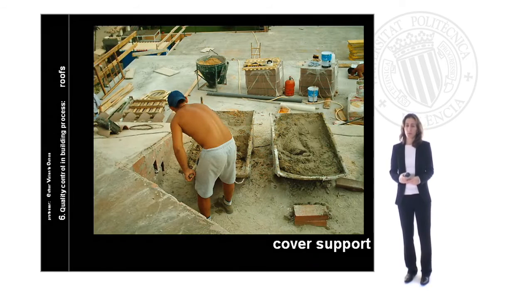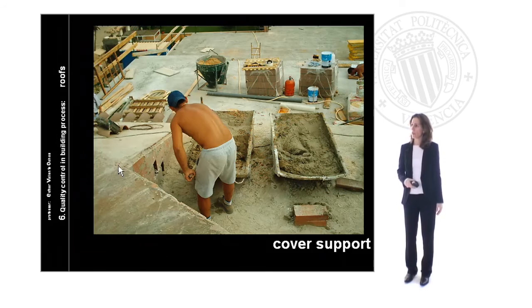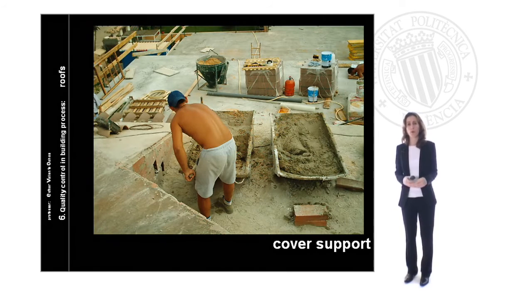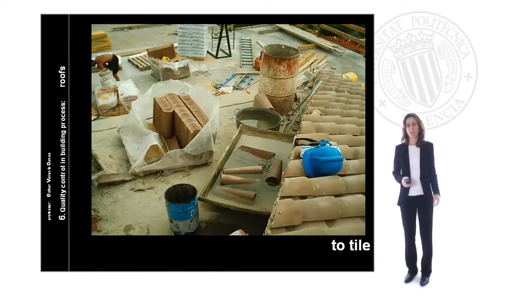After putting on the cover support, we have to make a surface with mortar. This surface is completely well done with a special mortar made with waterproof cement. This mortar regulates the surface and guarantees a good support for the next tile.